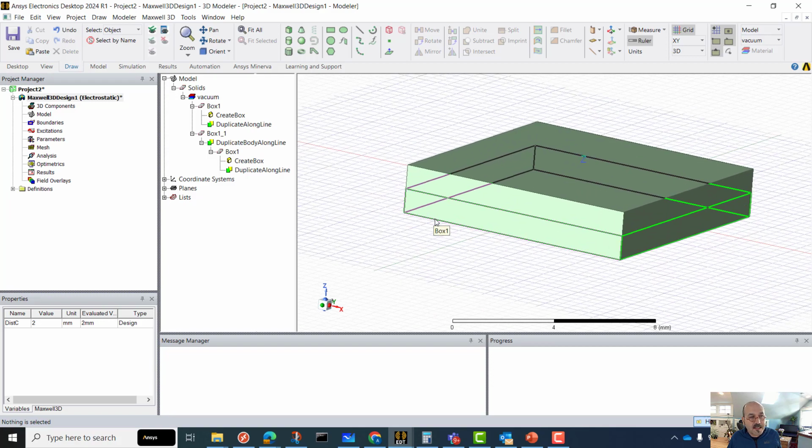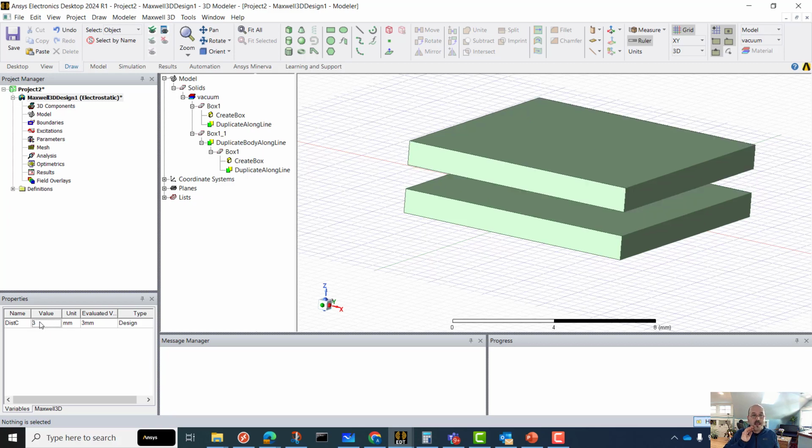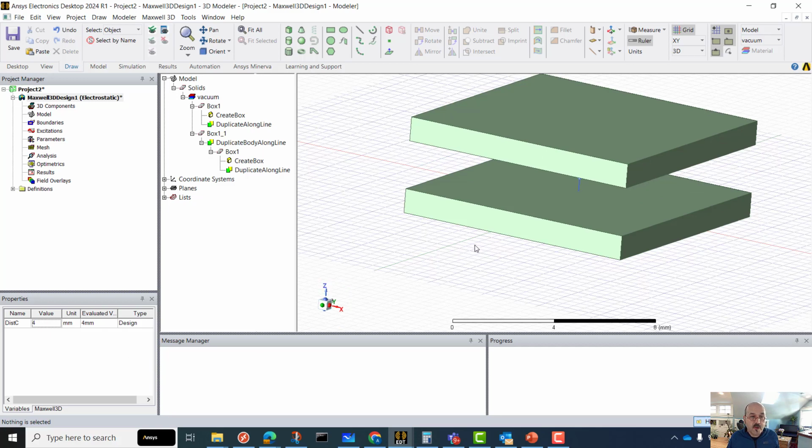This means they're in direct contact. So by saying distance -1 millimeter, I took into consideration the thickness of each of these based on that reference origin system. Okay, so the rule, if we use this, is that you always have to have a distance of something greater than 2 millimeters. So I would actually say 3 millimeters maybe would be the lowest we would want to go in this example. But you're free to make it 4 and 5, and you'll see it move accordingly.